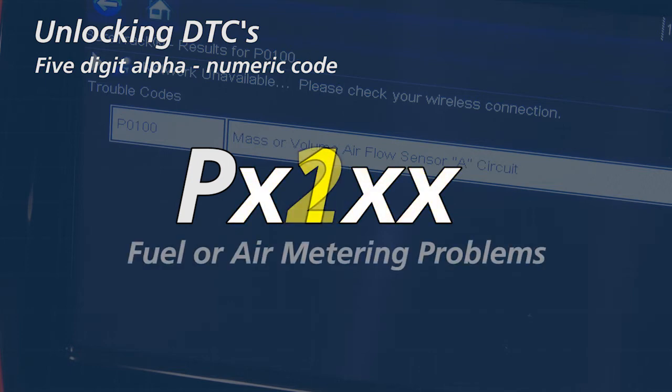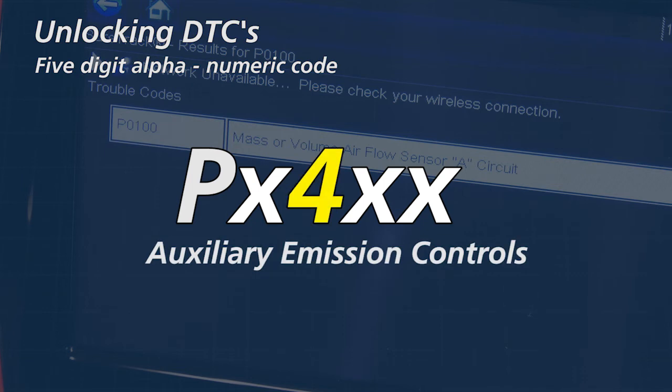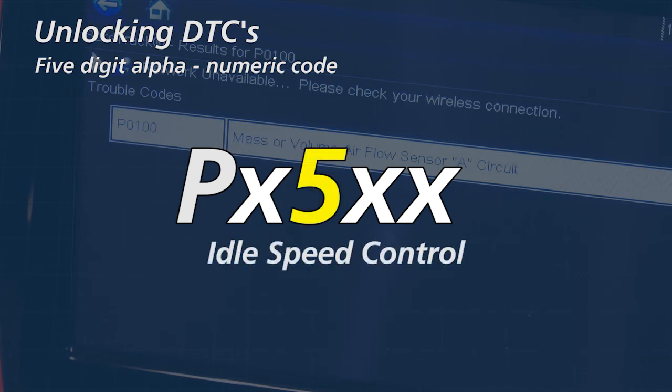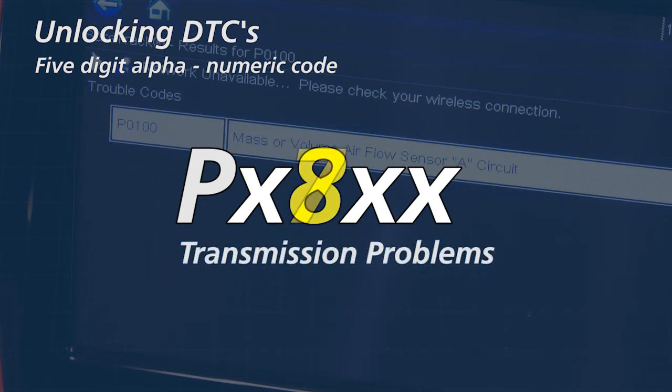Numbers 1 and 2 are for fuel or air metering problems. 3 is for ignition problems or engine misfire. 4 is for auxiliary emissions controls. 5 relates to idle speed control problems. 6 is for computer or output circuit faults, and 7 and 8 relate to transmission problems.